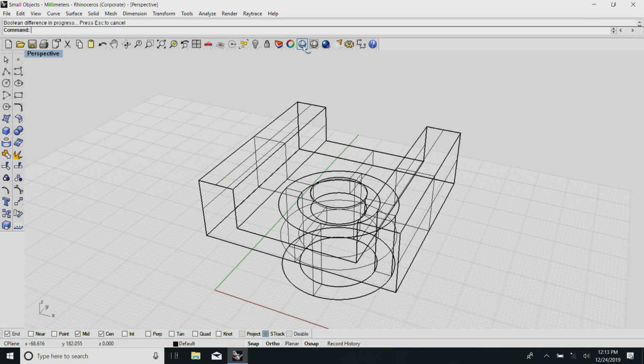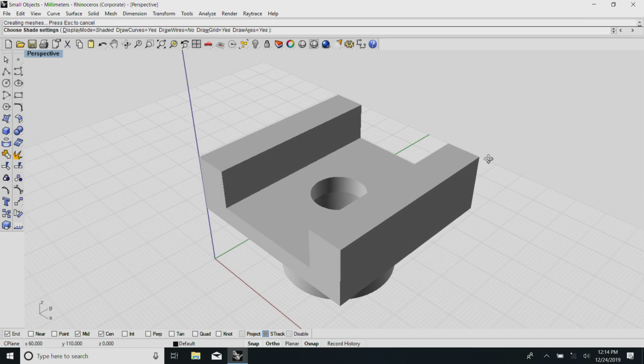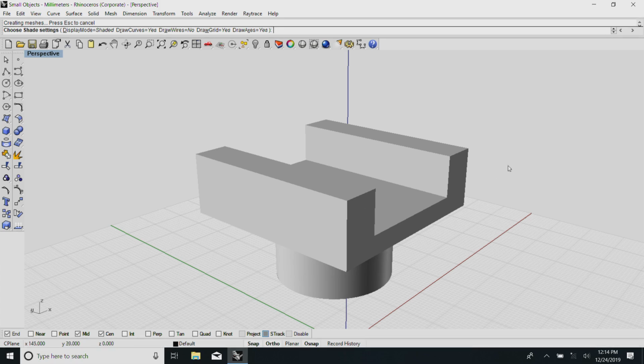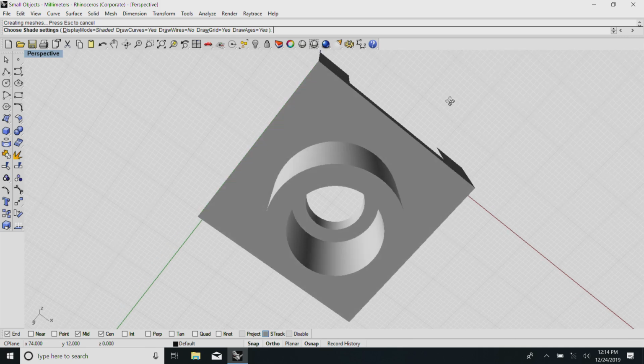I have the same object created by a different method. So, what is the difference? One of the first things in the difference is I have probably an extrusion, in this case a C channel of internal width of 31 mm, which is typically that 1¼ inch I am talking about, and this thickness really does not matter. I get things which are 3 millimeters and 4 millimeters wide. So, a C channel, I have used the profile of the C channel to take it forward and show you that the whole thing is possible, and at the bottom I have attached a tube to this.